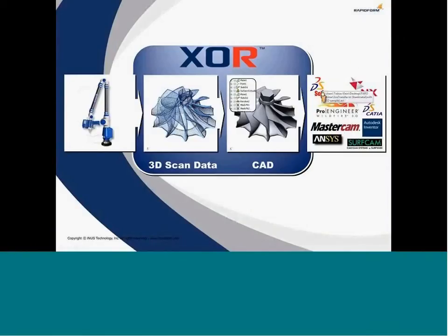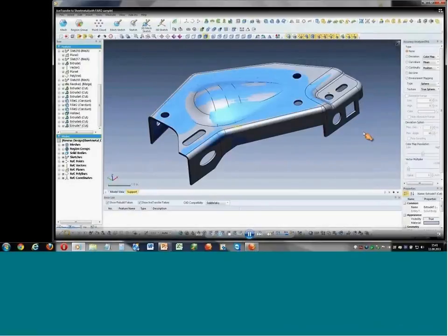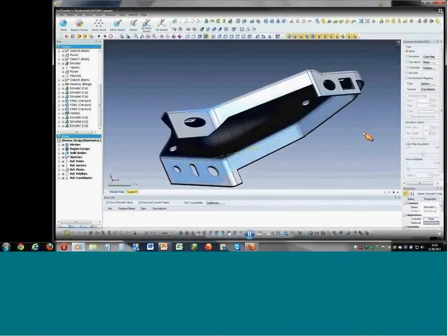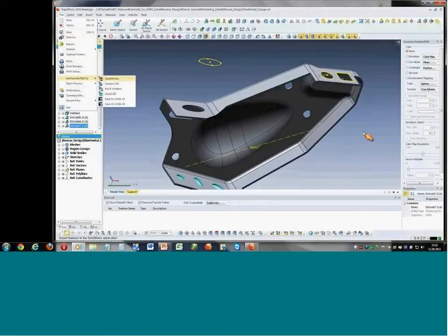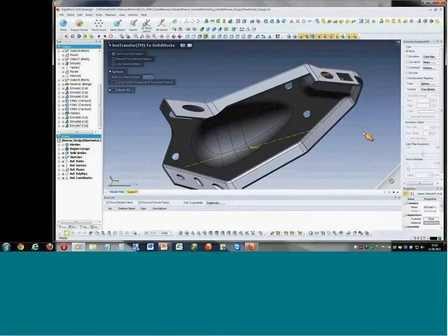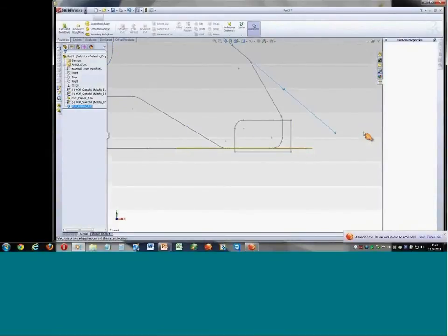And when we finished our CAD model, then we can go directly, now in this case, the model which I did before, we can directly transfer this model to a CAD application. So in this case, we transfer this model to SolidWorks. This is still inside Revit form. We have a look at our compatibility, which tells us during modeling which function is compatible with SolidWorks, and then we can start the live transfer to SolidWorks.